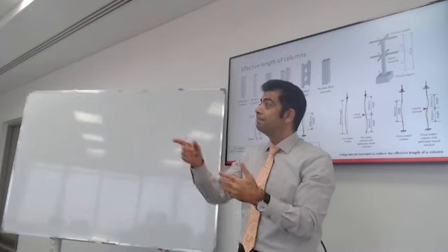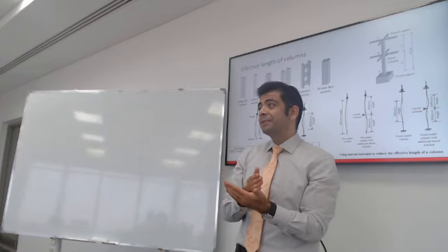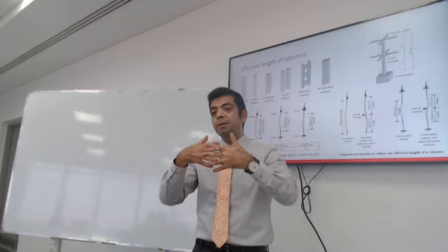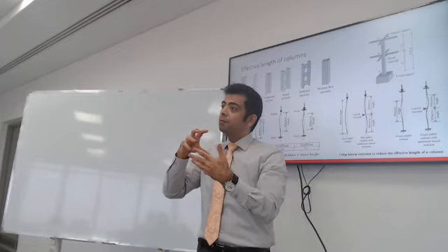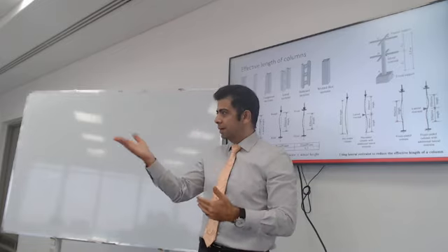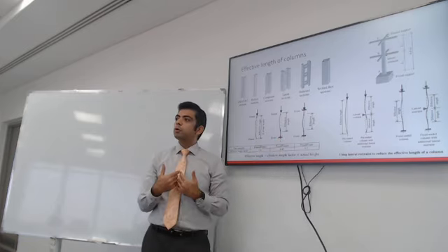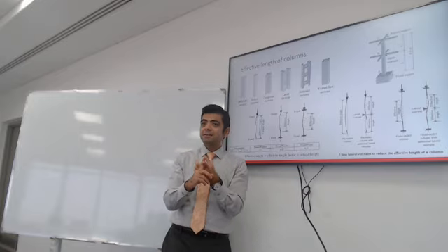Maybe the bolts with the red ring. We did that yesterday, the bolts and welding, for structural analysis when we were talking about rigid connections. Rigid connections are designed to be fixed. Pin connections are designed to be pinned. So you actually have to design the connection, so you know your assumption. I designed it with a few bolts, it's pinned. So that's step number 1.